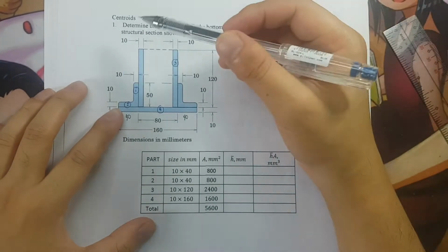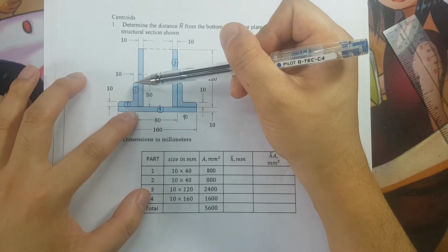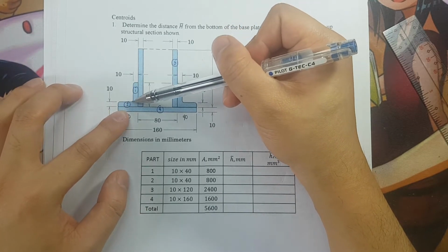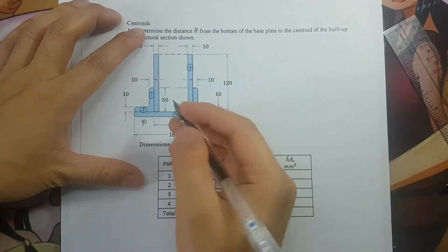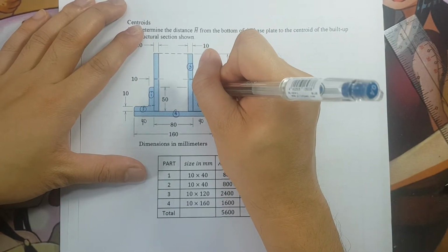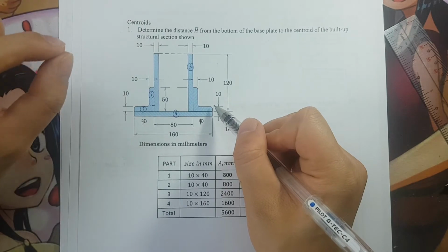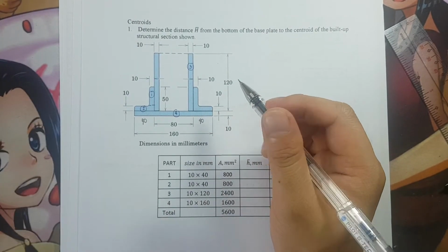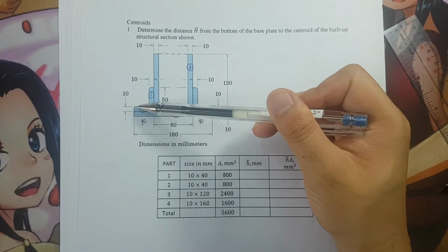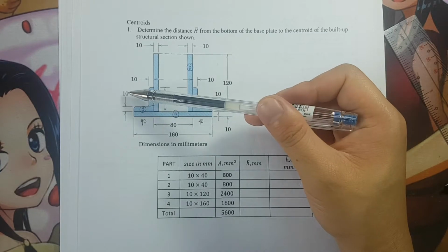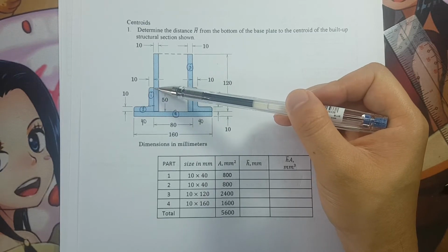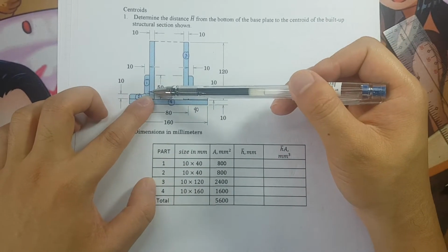The first thing to do, as I have here an angle bar, is to cut it into two parts. So you have here part 1. At this portion, I am going to cut the angle bar here. We are to neglect the curve here, the very small curve. It is negligible. Take note, the height here is 50, and the thickness of the leg members is 10. So 50 minus 10, that is 40. So the size is 10 by 40.